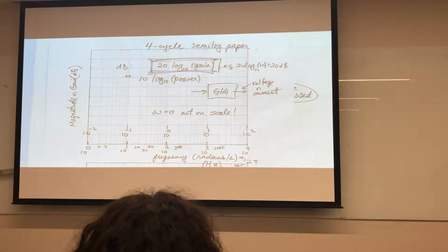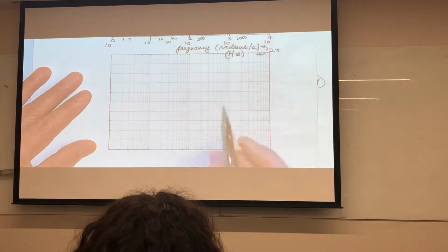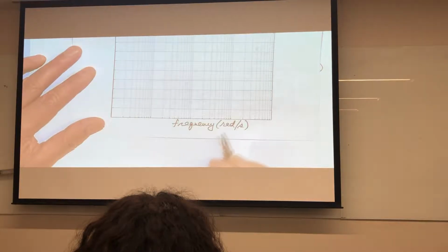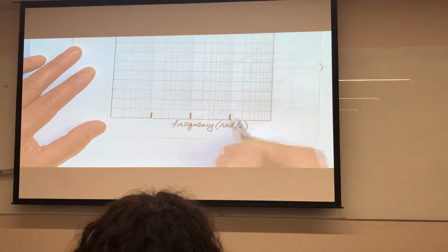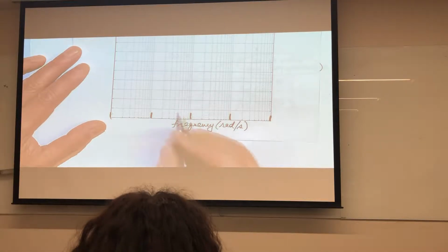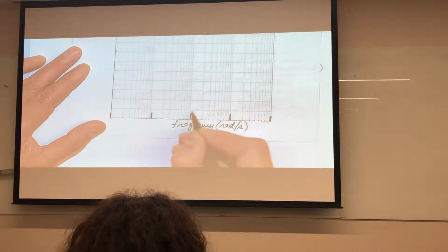The other diagram is also on the same axes, and so we're going to plot frequency down here, and in this class we'll default to the units radians per second. Find your major tick marks, okay, and put the exponents here. Okay, you cannot arbitrarily say, well, I'm going to put 10 to the 0 right here. You have to put the exponent right here.